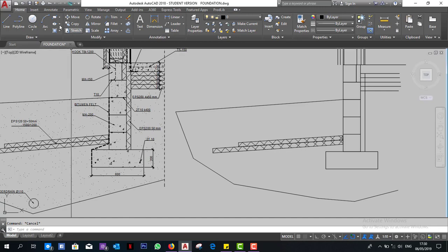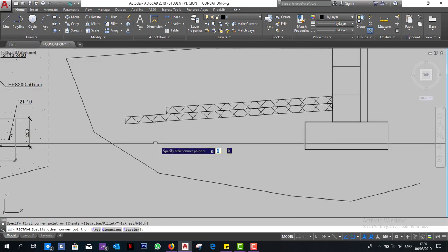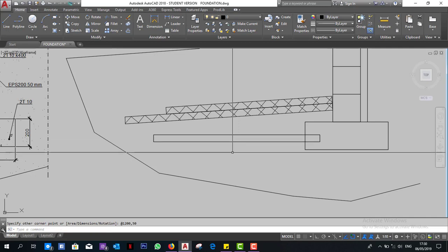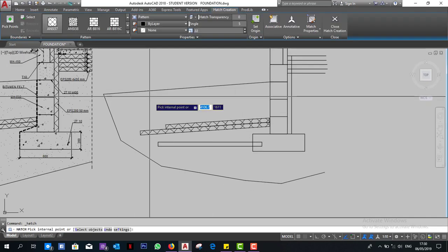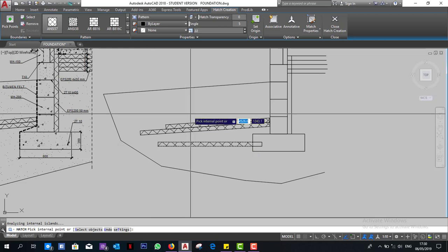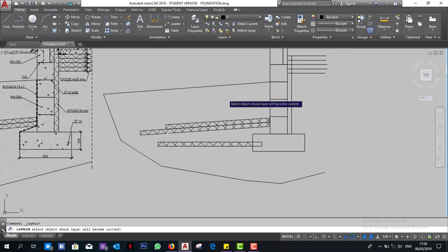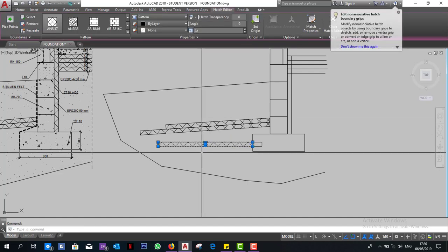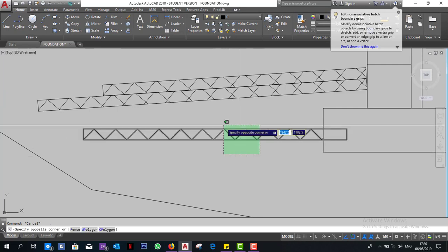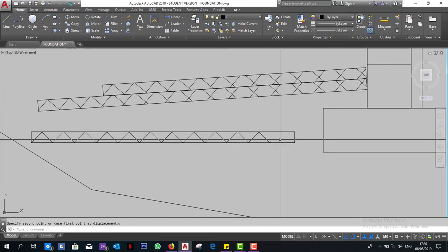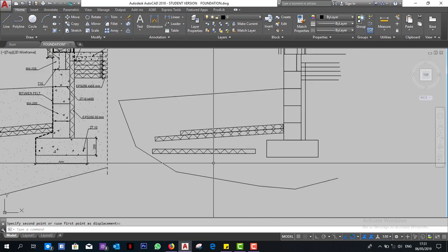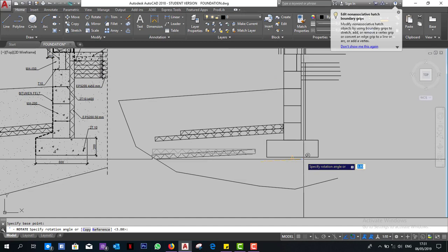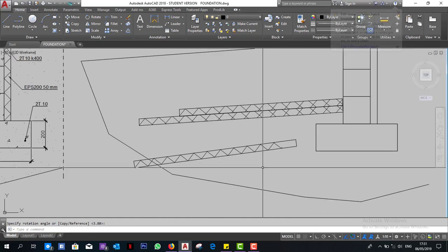For that reason, it is better to put the hatches when the rectangle is straight. If we go to hatches again and we place the angle 0, it would be good. Then you can rotate it and the direction will be the same, but in our case it doesn't matter.